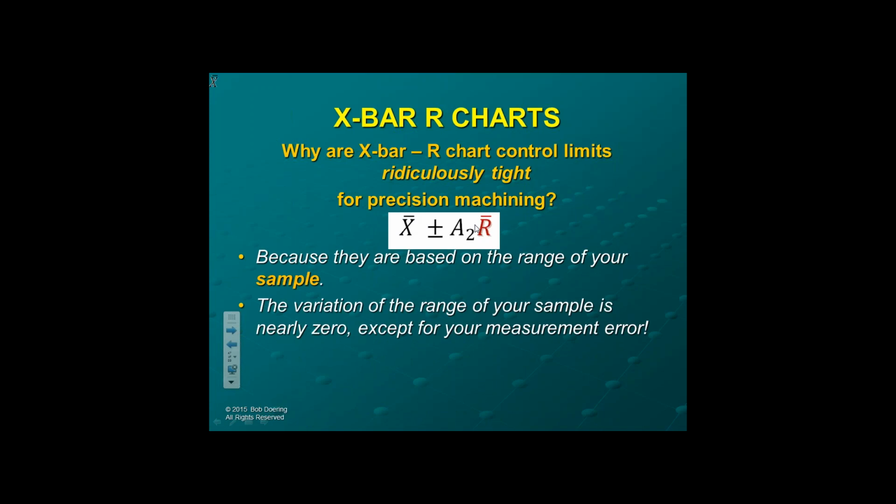The variation that you are going to see, though, is measurement error. Not gauge error, measurement error. Again, that goes back to the fact that you only took 1 diameter out of an infinite number. So the only variation you're seeing is the variation based on the issue with roundness, which has nothing to do with variation over time. That's a within part error.